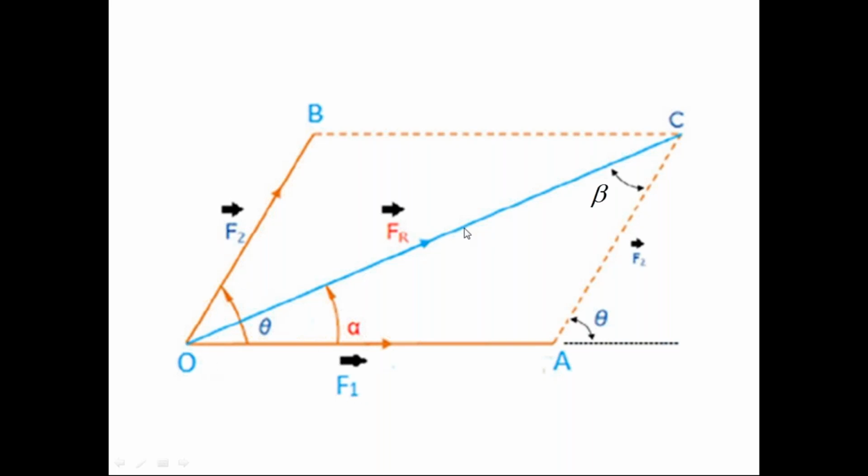The diagonal of the parallelogram passing through this point of intersection of the two forces gives the resultant force FR bar of F1 bar and F2 bar. This procedure is the parallelogram law of forces. So by using that parallelogram law of forces, you can find out the resultant force of only two coplanar concurrent forces. You can apply this parallelogram law if the rigid body is subjected to only two coplanar concurrent forces F1 bar and F2 bar. This is totally a graphical procedure.